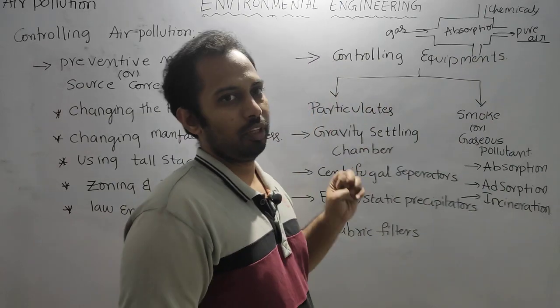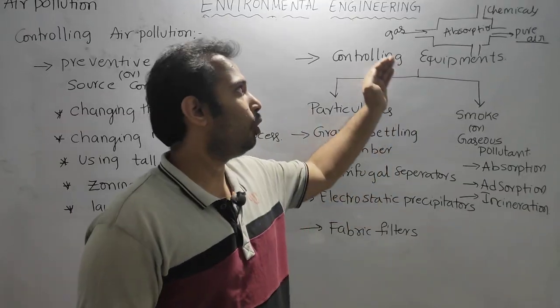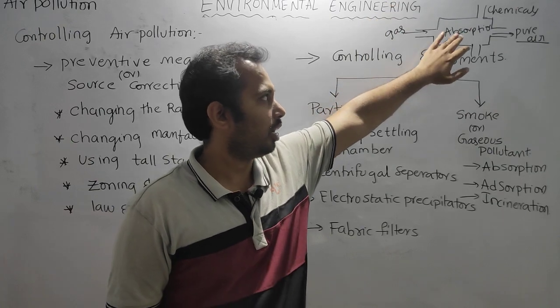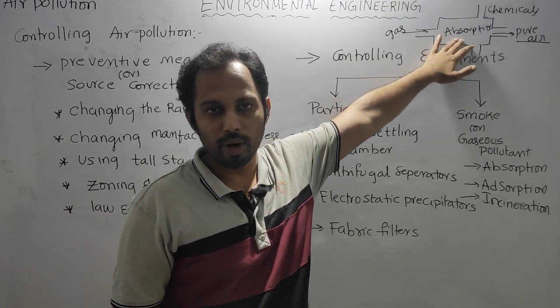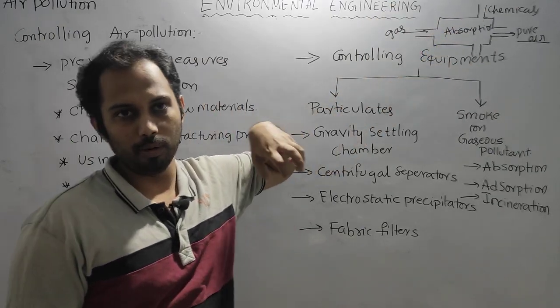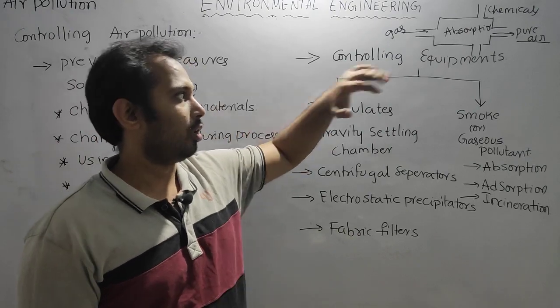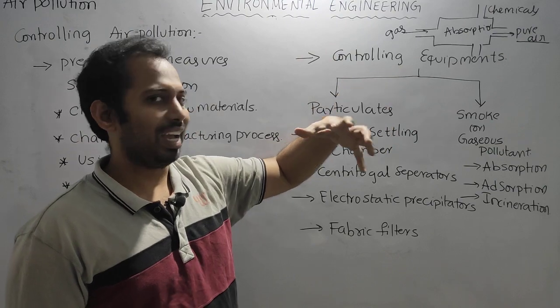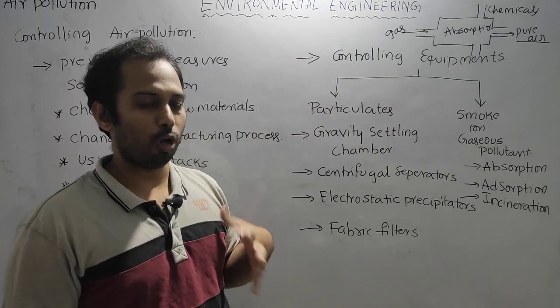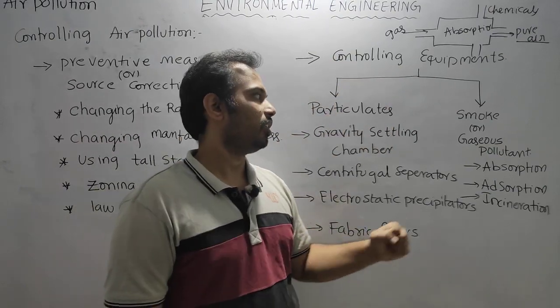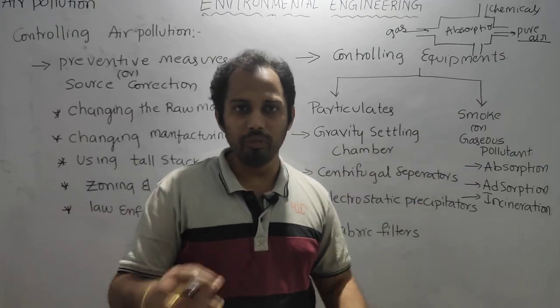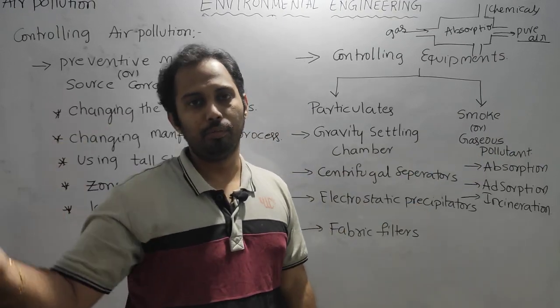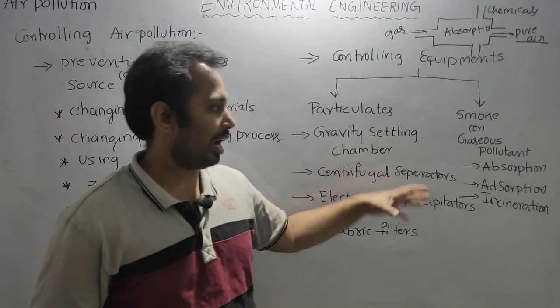And adsorption: we send the same into a medium, like activated carbon, which we discussed. Activated carbon is a good adsorbent. But here we may use a different kind of material which adsorbs, not absorbs, the gaseous pollutant and leaves the fresh pure air outside. That is called adsorption.